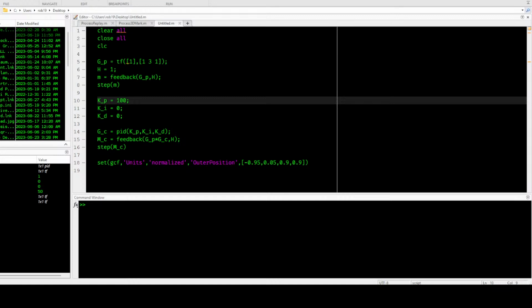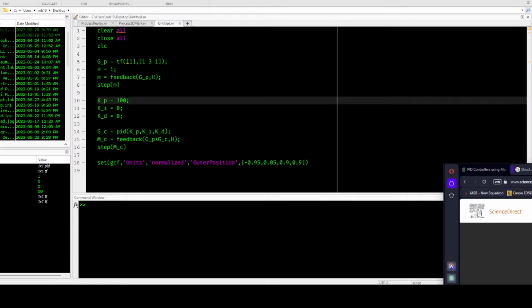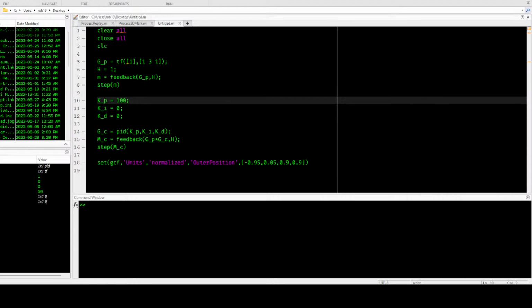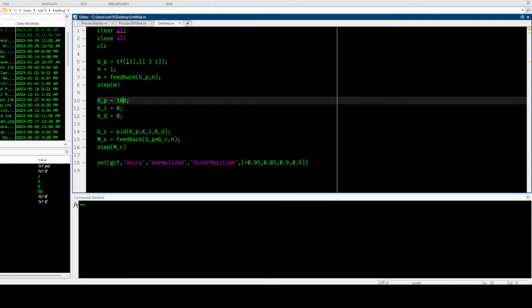Because the spring and the damper behave on two very different properties, but they're very important to controlling a car. So a spring responds to a change in position. If you squeeze a spring half its length, you get half as much force as if you squeeze it its entire length. The amount of force that comes out of a spring is proportional to the amount that it's squished. Does that make sense?